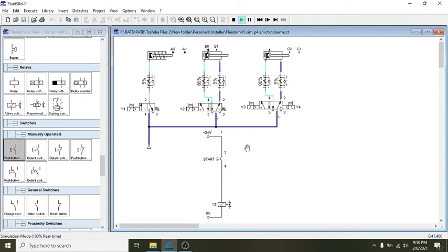Also, if we try to observe when you immediately release the normally open push button, there is the tendency that the cylinder will not be able to reach the farthest point it can cover.